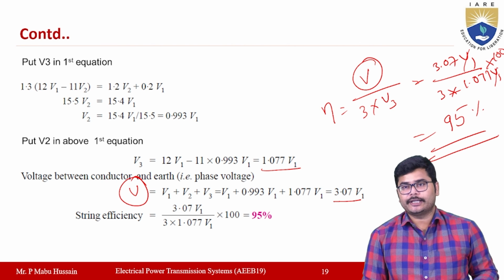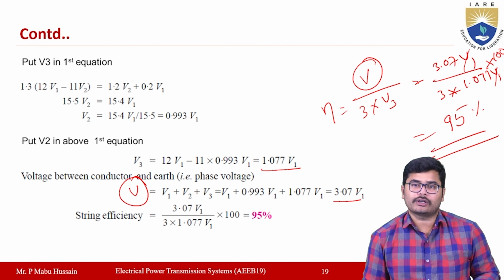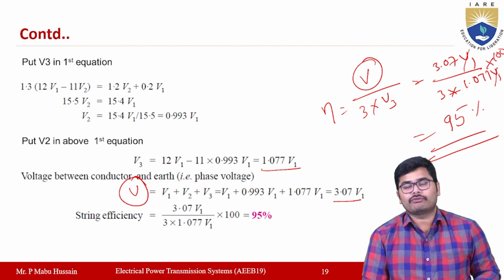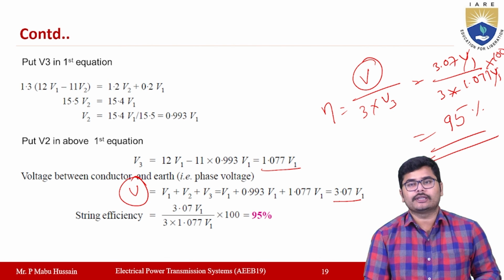So this is how we can determine the string efficiency for different problems, and you can even find out the voltage distribution. Right? If you want the string efficiency, then obviously we have to determine the voltage distribution across each unit. Okay, so this is how we can determine the string efficiency for different cases.